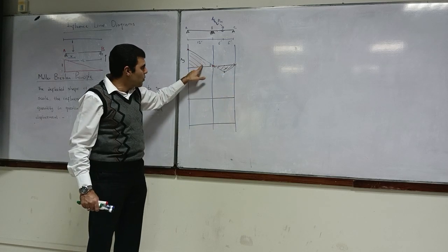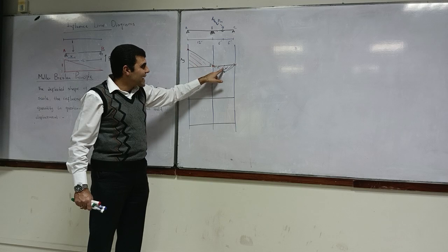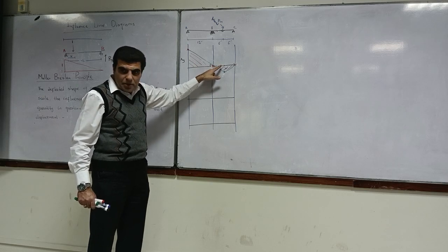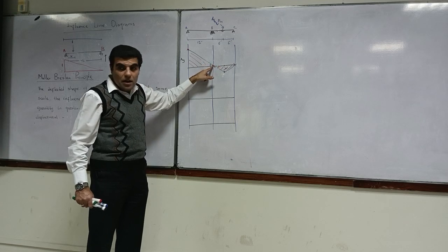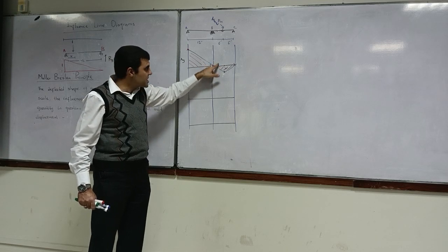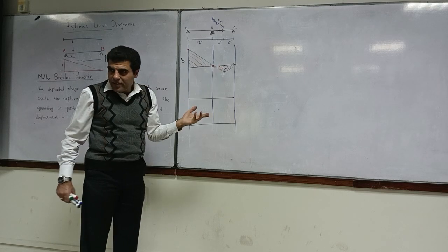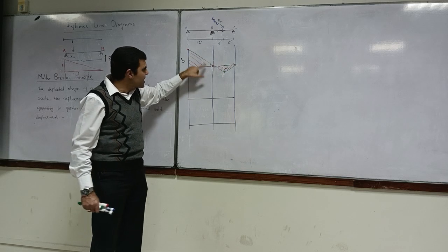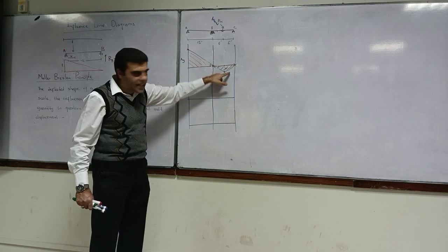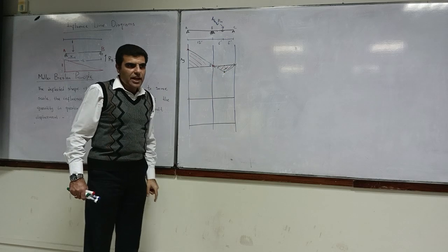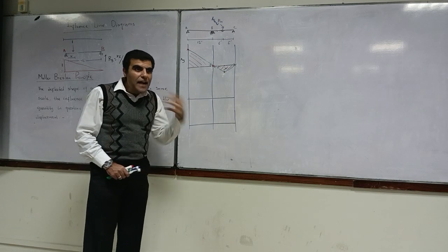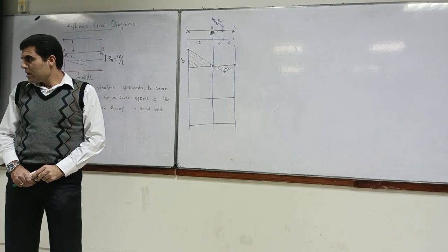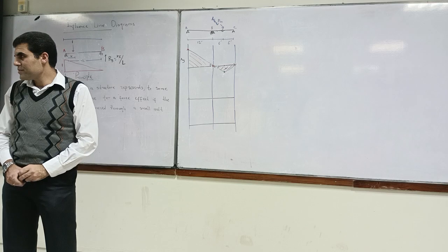So I'll find out the middle one. Then I can do it for this one also. I can put it over here at one point between the plastic hinge, between the hinge and the point B. I can put this over here and find the reactions again. So I can find this magnitude, this one, and this one. I'll find everything. So if I want to do using structure analysis, I can do it. Yes, you have to find out reaction.